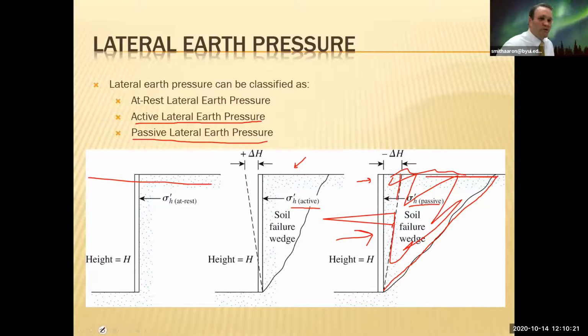And so we're talking about lateral earth pressures. And so there's coefficients because we know that we can calculate the verticals. We've been doing good at that. We've been calculating that for a couple of weeks now. We know vertical stresses, and now what we're learning is, there's a horizontal component to that, but it's not just 1/2. That's a rule of thumb. There's actually a calculation. You can figure out exactly what the at-rest pressure is, the active lateral earth pressure, or the passive. You can calculate these, and there's 3 different ways to figure them out. And so that's what we're going to cover in today's class.